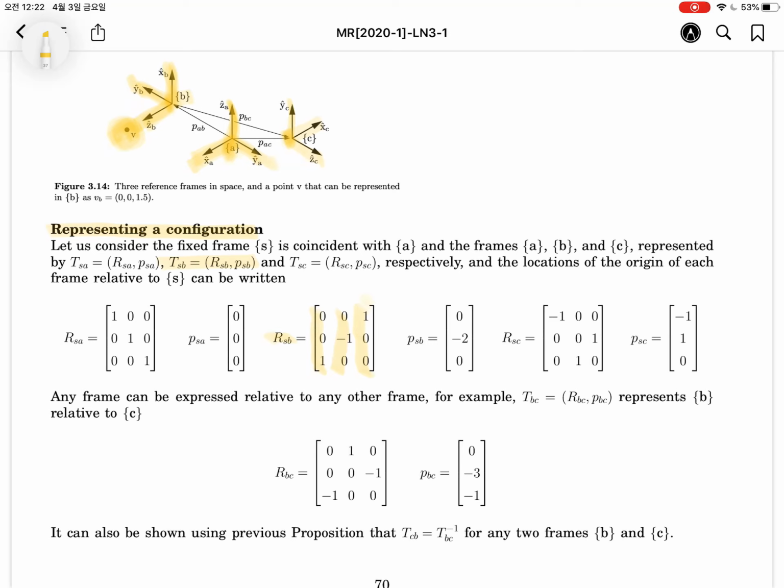Okay, let's assume that this is the coordinate of the origin of the B frame in terms of the A frame. Let's assume that this is 2 units in the minus y direction. So 0, minus 2, 0. Okay, let's apply this kind of concept to the base frame C. X can be read using the minus x, so minus 1, 0, 0.